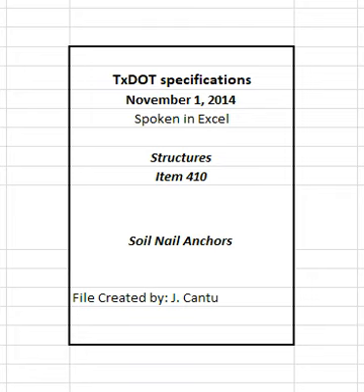2.3 Reinforcing steel. Use materials that meet the requirements of item 440, reinforcement for concrete. Provide epoxy-coated reinforcing steel bar of the size and grade shown on the plans for permanent walls. The minimum allowable epoxy coating thickness is 12 mils. 2.4 Bar couplers. Provide bar couplers that develop the full nominal tensile capacity of the soil nail bars as certified by the manufacturer. 2.5 Nail centralizers. Provide expanded slit PVC centralizers with a minimum diameter of 1 inch less than the nail hole. Wheel-type centralizers will not be allowed.